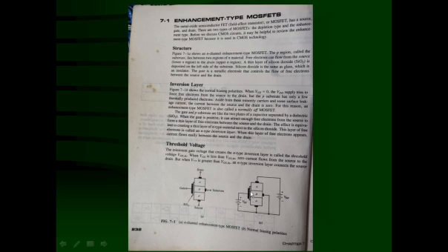Normally, how is the biasing of the circuit done? The substrate is connected with the negative terminal of the battery. You can see that the positive terminal of the battery VDD is connected with the drain, that is N-type material. The negative terminal of VDD is connected with the source. The N-type material has an excess of electrons, which are supposed to move because of this battery force. The electrons should move from source to the drain. That constitutes the current from drain to the source, which is called conventional current.